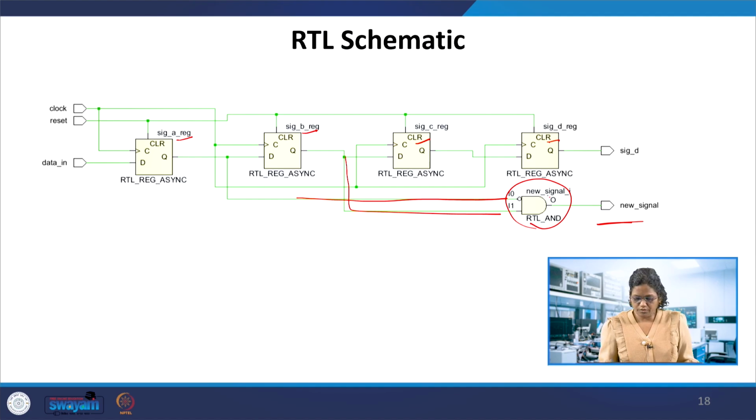Because of this unregistered signal, it won't be stable with respect to the clock like the previous case; here it is only combinational logic. So if you declare a variable inside the passage of the clock, it would infer flip-flops here, otherwise it would be unregistered. The combinational logic can be separate, but it is a continuous assignment now. It is not with respect to the passage of the clock. It is a continuous assignment. What is available over here will be taken here at the new signal.